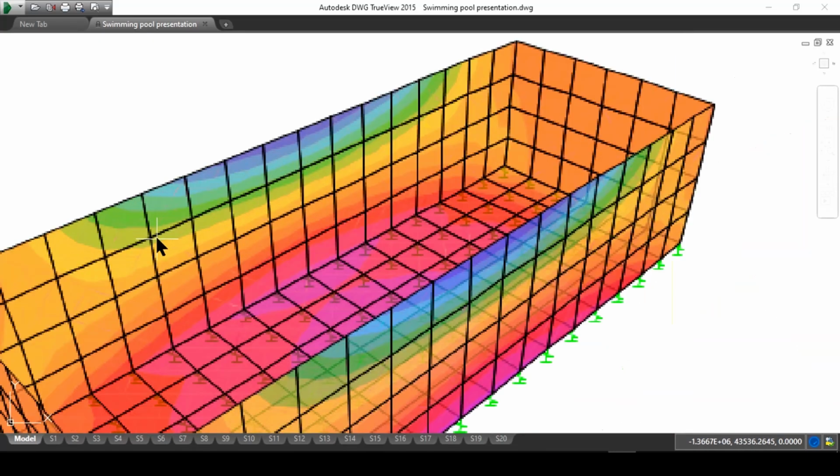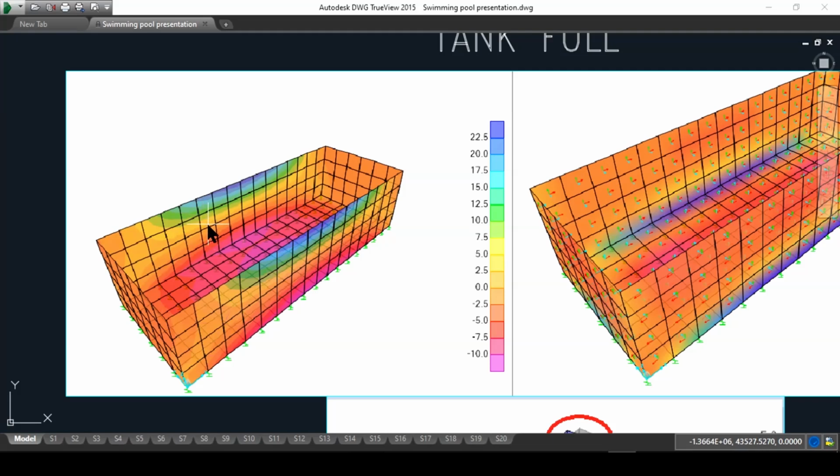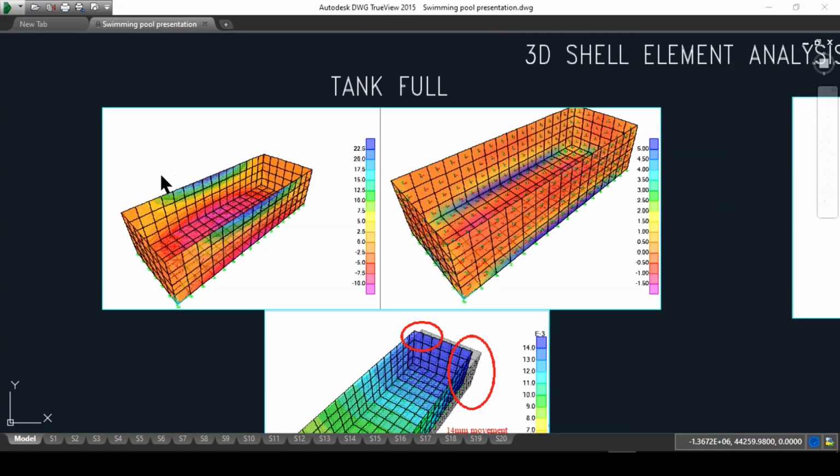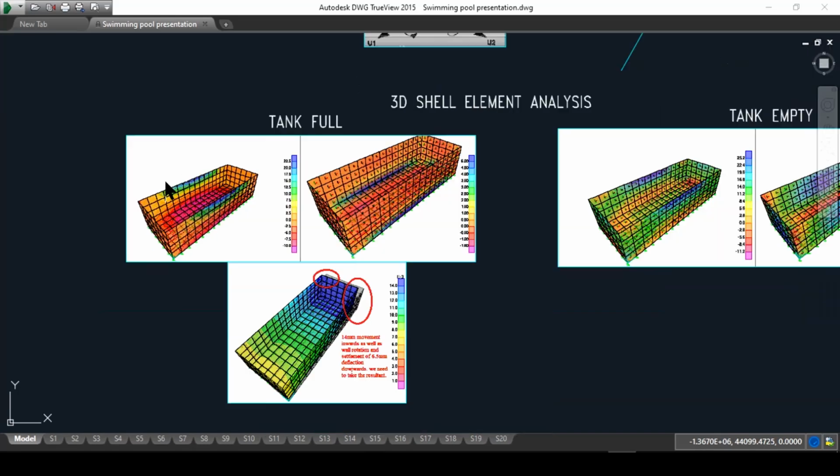And just imagine every mesh here has a node, has 4 nodes. So that means every mesh has 24 degrees of freedom. And just imagine how many degrees of freedom the whole tank would have. So that's why using stiffness method to work out the translation and the rotation at every node is probably the best way. And most of these finite element programs use stiffness method.